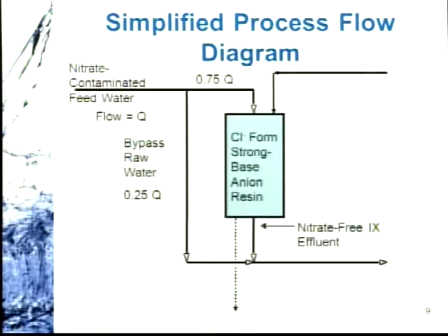So you've got your nitrate-free ion exchange treated water on the back end of that, and then the blended water, typically here, you know, in a nitrate as N value of 5 to 7 milligrams per liter, or say 25 to 36 milligrams per liter as NO3.